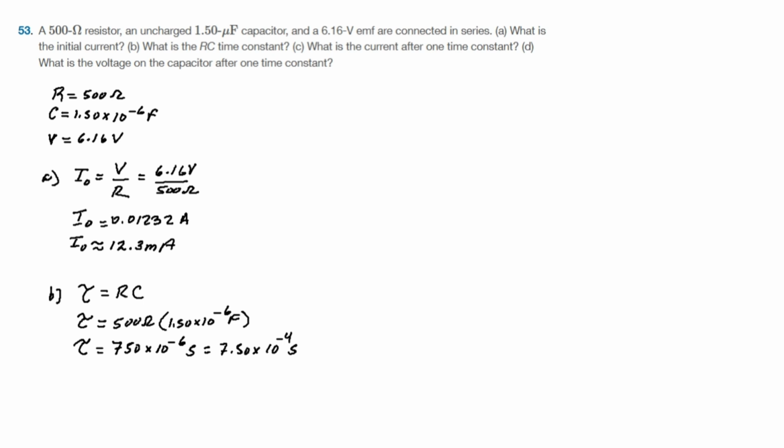But also, my capacitor was a capacitor of 470 microfarads, and they are using a capacitor of only 1.50 microfarads. So they have an RC circuit with a very small resistance and a very small capacitance. So that's why the time constant is that small.